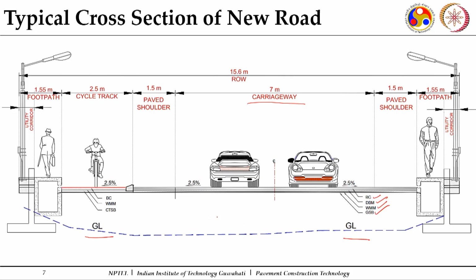So, when you are compacting each layer, you know from your drawings the finished road level, especially at the center line. With the use of these side slopes or cross slopes, I can work out the levels at these locations. Then, working out my pavement crust thickness, I can work out the levels at these points. Then, considering how much fill is required, I already have the natural ground levels or original ground levels with me.